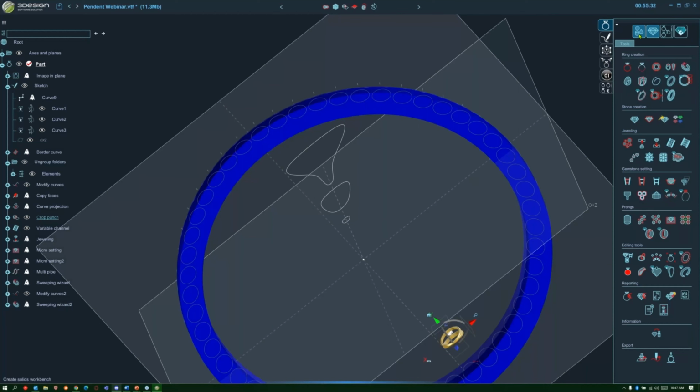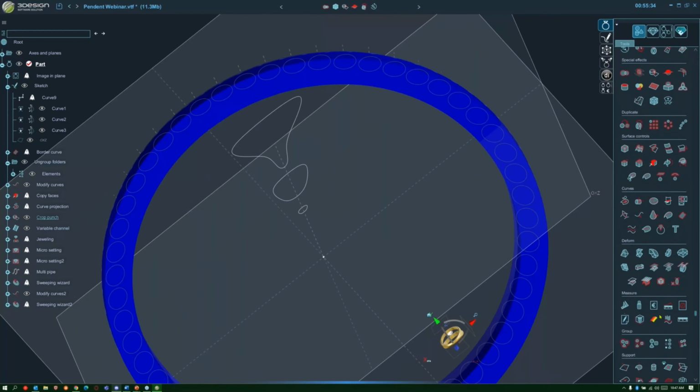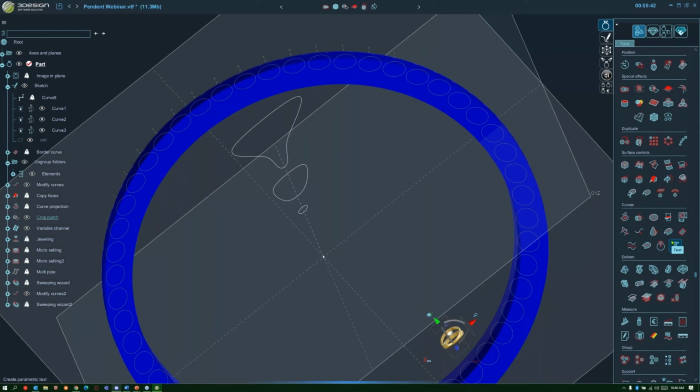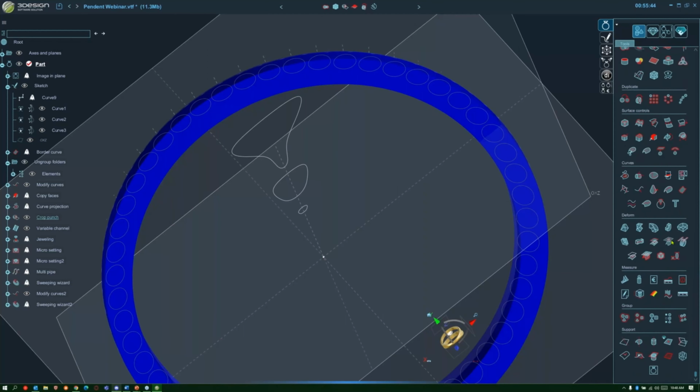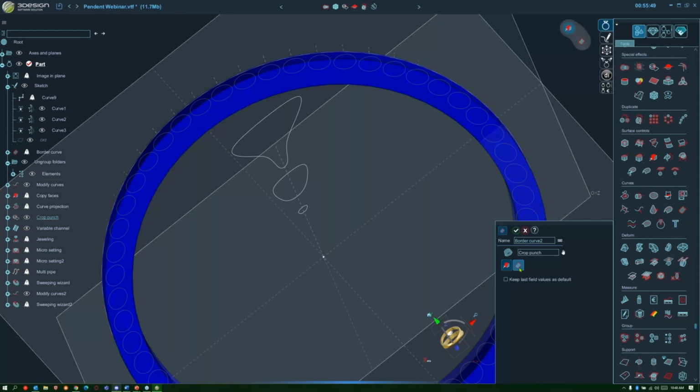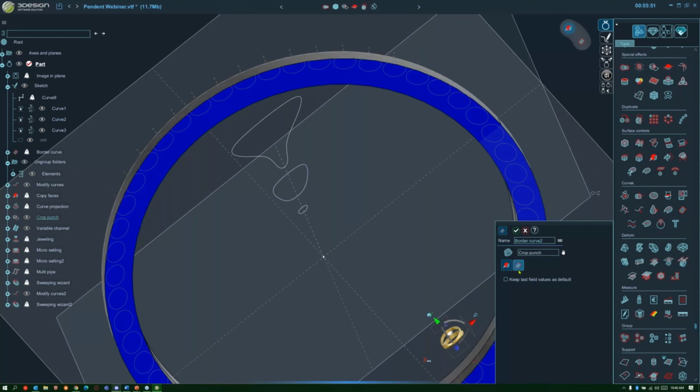All right. Okay, so first thing I'm going to do is set some more borders here for the bottom. I already have some borders on the edge, but I want to offset those a bit. So we're going to go into my curve section and choose the border curves here, extract borders. And we're going to go to that bottom surface again, or this is a different bottom surface.